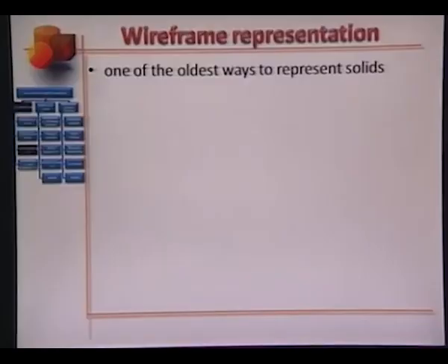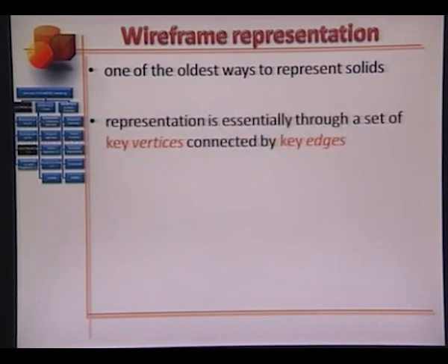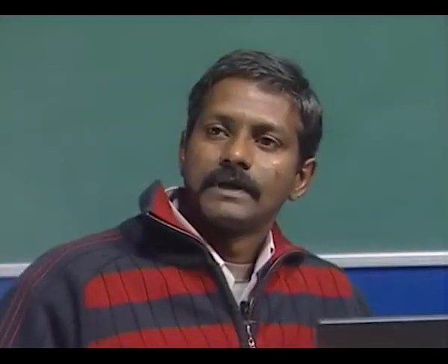First, the wireframe representation. This is one of the oldest methods to represent solids. As the name suggests, the representation is primarily through a set of key vertices connected by key edges. Remember, here we are not talking about faces, only vertices and edges.